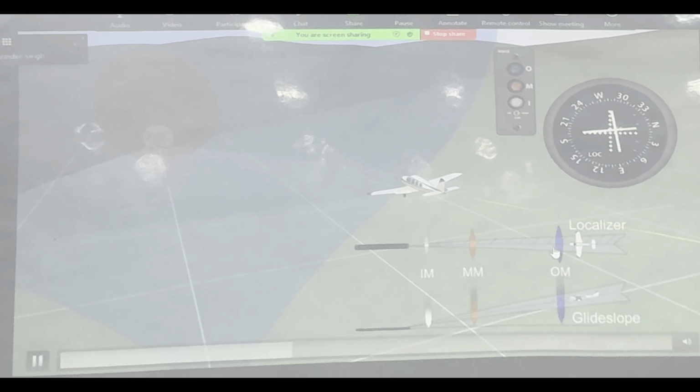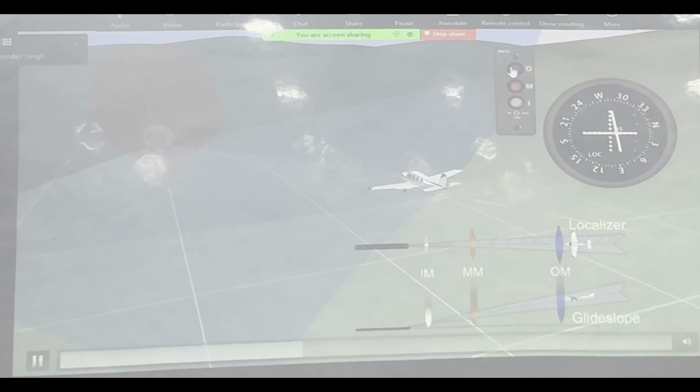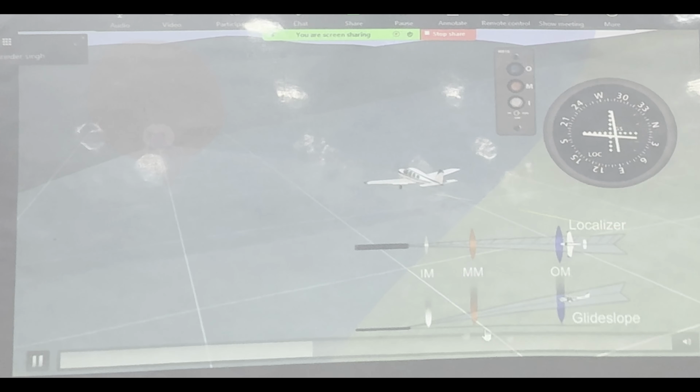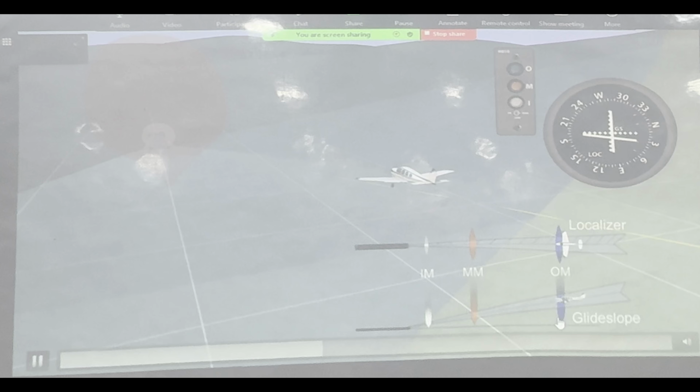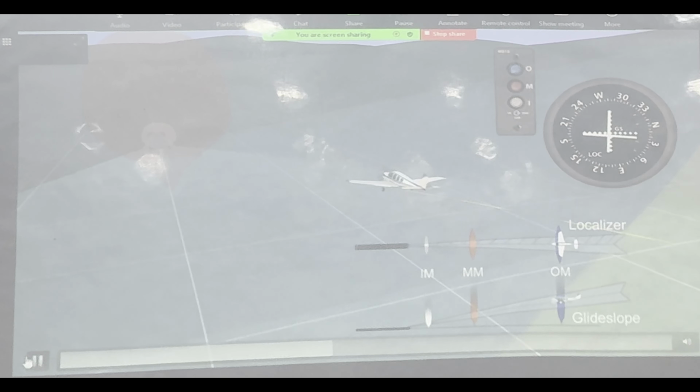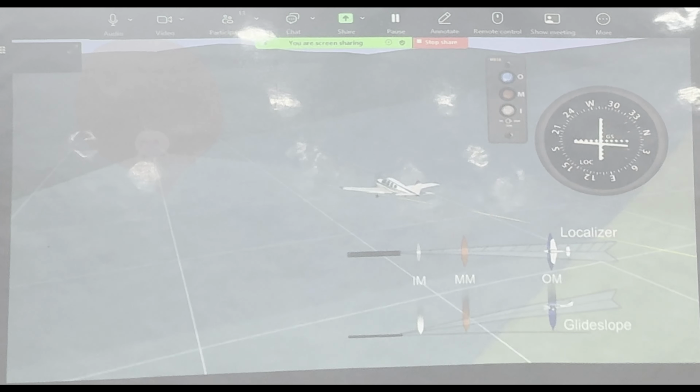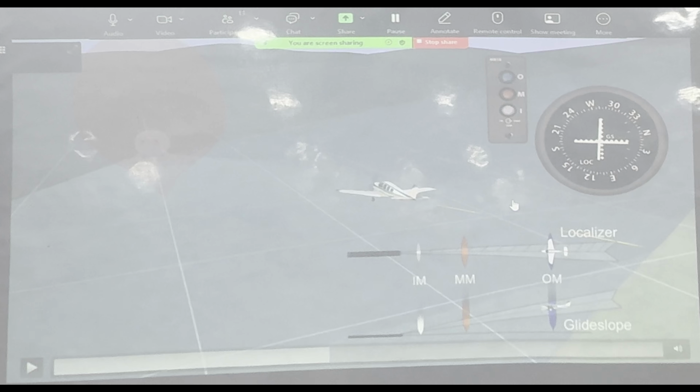So when the aircraft comes exactly over this, you will have this light and audio, and this distance is given on your charts. You will see those. This is the audio which you hear when you are over the marker: dash, dash, dash, plus this blue light comes on. This distance is given in the chart. You know how much this distance is, so you know how far you are from your touchdown point.